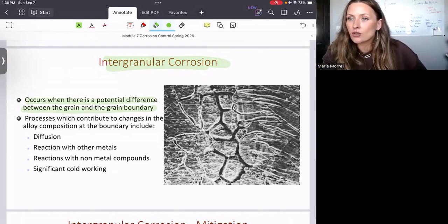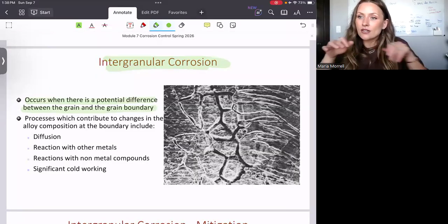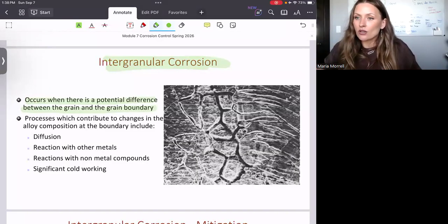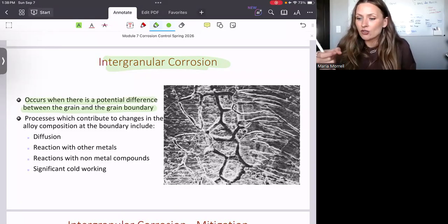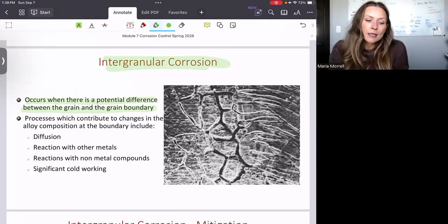Multi-phase alloys, we already looked at that, right? Whenever you end up with doping, you always need to make sure that whatever is introduced in the metal has to be dissolved and dispersed equally across the entire material. You never want to have chunks here and there because these islands can have a different potential with respect to the adjacent host metal, right?